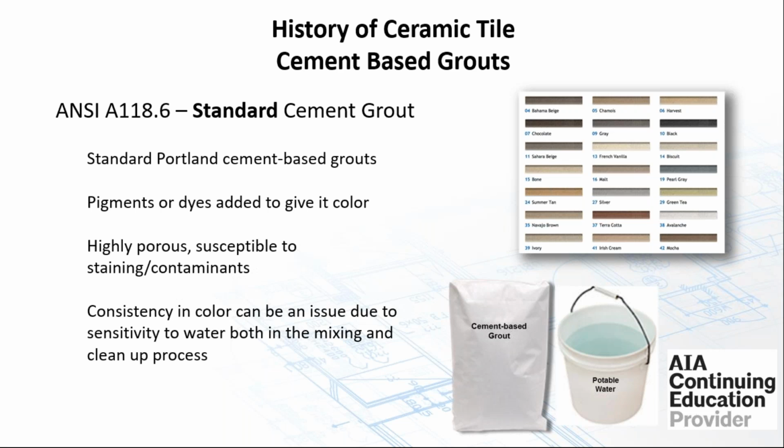So typically what happens with a Portland cement grout is that the installer mixing it up will add so much water to it. And on a hot day, he's feeling, oh, this is going to set up, so I'm going to add a little extra water to it. Or once he's got it down onto the substrate and he starts cleaning it up and it's starting to set up on him, he uses more water to clean it up than necessary.